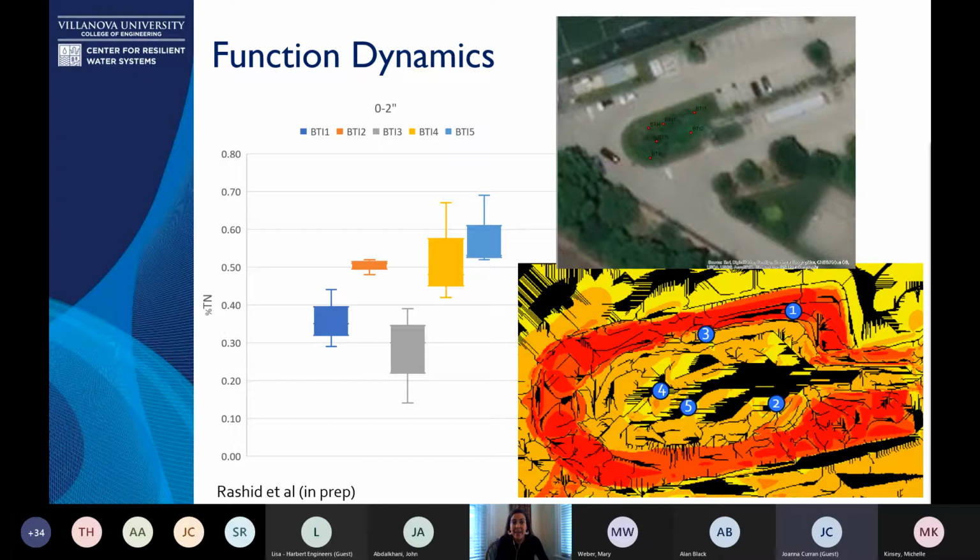This is 20 years old. And for the past 20 years, it's been working great. And so we started looking at the soil samples here, Dr. Sample Lord and I, and we also modeled this with ArcHydro to see where you might have more flow accumulation and less flow accumulation. And what we saw was that the areas that are being inundated frequently and have a higher shear stress running off of it had lower rates of nitrogen. But areas where you had more ponding, areas like 4 and 5 that are in the basin here, there your nitrogen percentages were higher. And so you can see 4 and 5 are quite a bit higher.